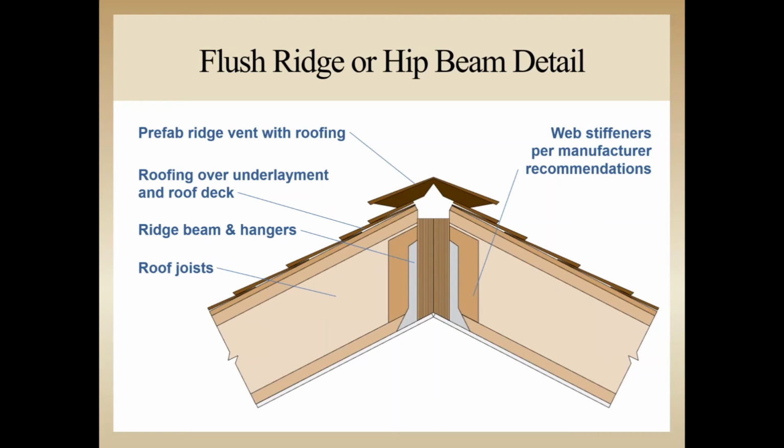Check with your manufacturer for a specific recommendation in those cases. It's critical that the required depth of insulation be taken into account when specifying joists used in a roof assembly. There must be enough remaining depth for the correct airflow to occur when ventilation is required.